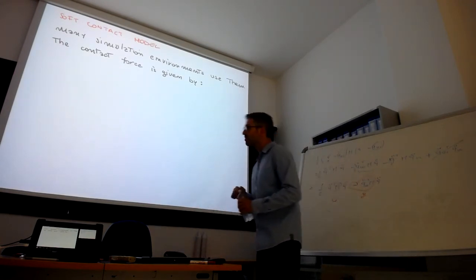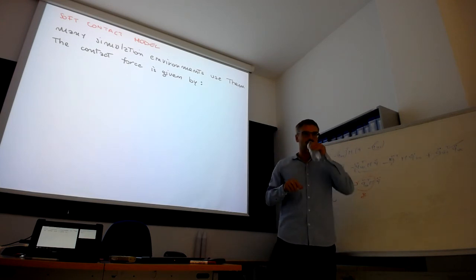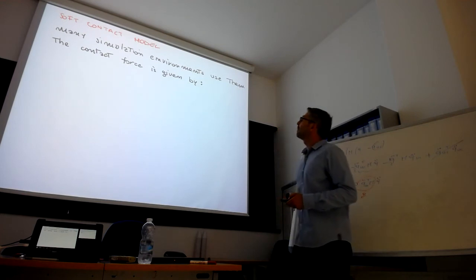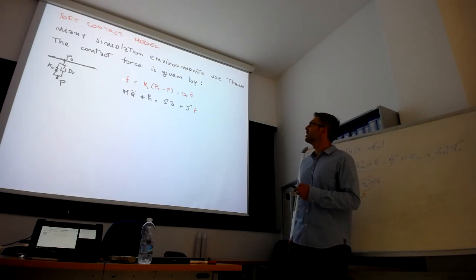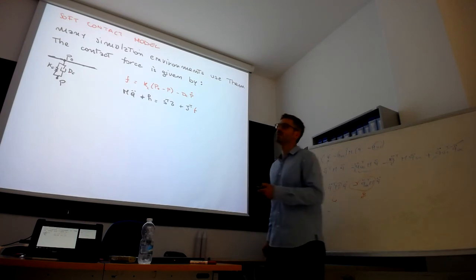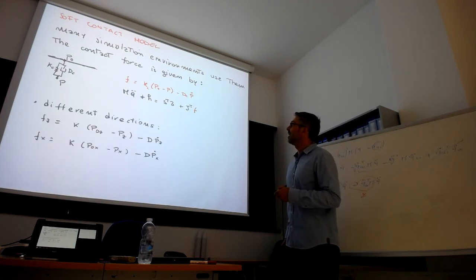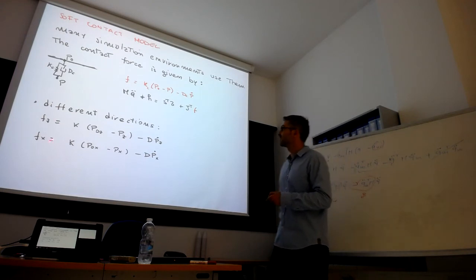Now, we discussed the rigid contact assumption, but there are many simulators, I think Gazebo is one of these, that use a soft contact model. In this case, we already talked about it previously. We model the contact as a spring damper, for example, and the force will obey a specific equation that links its evolution to the penetration between the bodies, in this case, for example, the foot of your robot and the floor. Then you can put it there and solve for the acceleration, compute the motion of the body, and then you can again take the force and iterate.